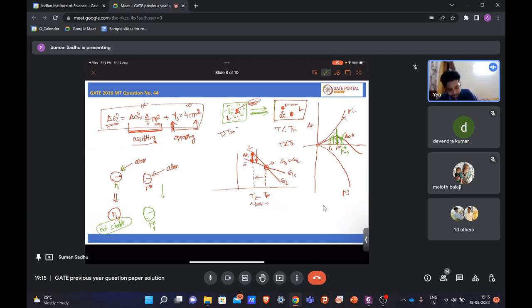So that means it is favorable. So this is stable. So any cluster having a radius below r star is not stable, because adding one more atom will destabilize it. But if that cluster reaches the radius of r star and you add one more atom, it will stabilize. So that's why this critical point is called the critical nucleus size.